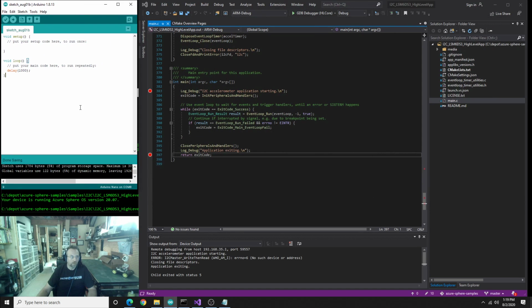All right, so this is just an empty sketch. What's the first thing we need to do? That's right. We need to include our library, which is wire.h. Yep, you got it. Cool. Let's press Control S to save that, and click on the upload button. We're uploading it into our Arduino now, and it finished. It's done uploading. So the Arduino is now ready to rock and roll.